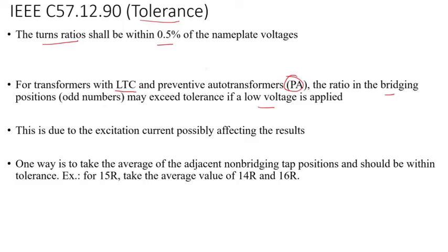So in other words, if you have the regulating winding for the tap changer, you're going to have turns and so on and so forth. If you have, say, 32 taps, 16 above and 16 below, with 10% above and 10% below voltage change, then if you do it with the PA, actually you just need 8 taps basically.